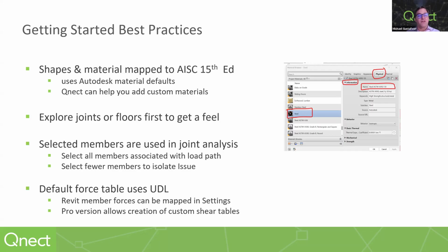And the cool thing with our tool, this is number 3, is the members. Look at the members being selected. If you want to be thinking about the load paths, right? If there are axial forces in your members, be selecting the members on the other side of the column, for example, or the other side of two beams coming into a girder, because we want them to talk to each other, right? So make sure you're selecting enough elements so that the load paths can be resolved.